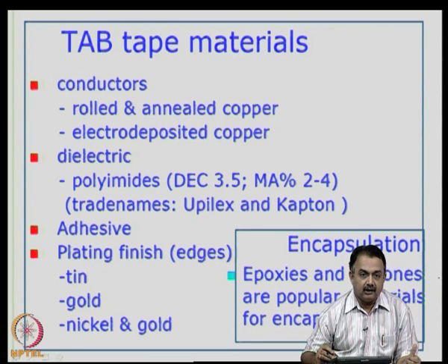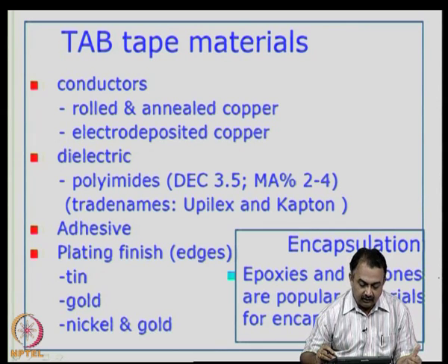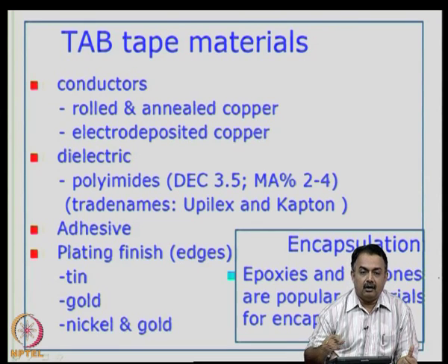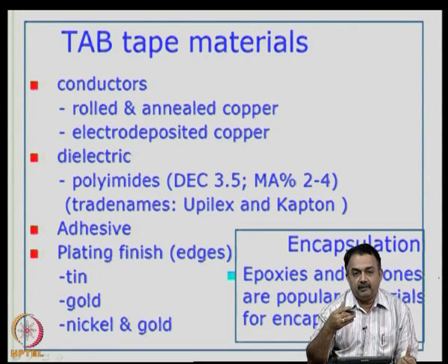The dielectric that is normally used is a polyimide tape whose dielectric constant is around 3.5, moisture absorption around 2 to 4, which is fairly high compared to epoxy. And some common trade names, UPILEX and Kapton, are commercially used. Then an adhesive will be used, because on the polyimide tape the lead frames are fixed at the manufacturing site.